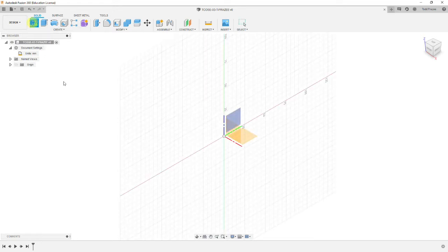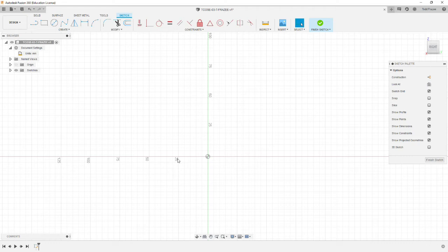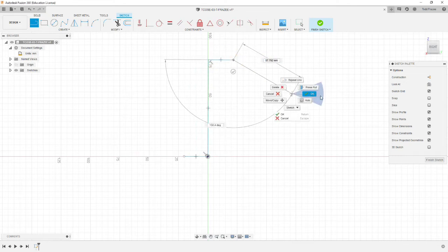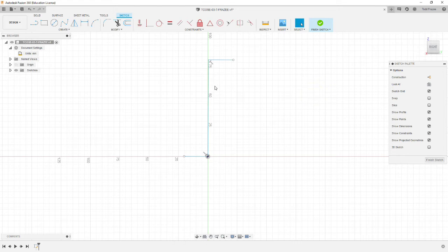Now we're going to create our sketch. Because this primary sketch is in the side view, we're going to sketch on the right side plane. We're going to start off and draw our S profile. Doesn't have to be perfect, but we do want it to anchor on the origin. Okay, so we have this Z shape, resembles the part. We want to make sure that the blue line that's highlighted is vertically constrained and constrained to the origin. We're missing a line. One more line there.